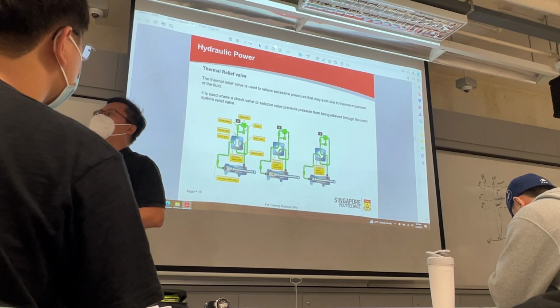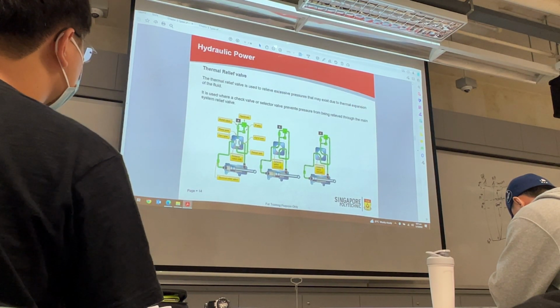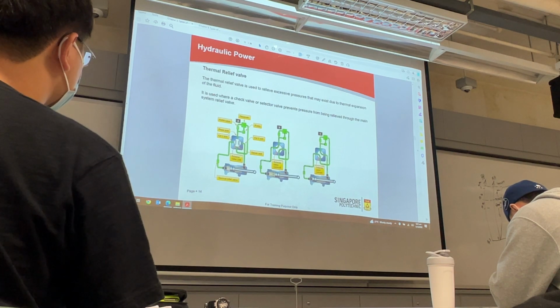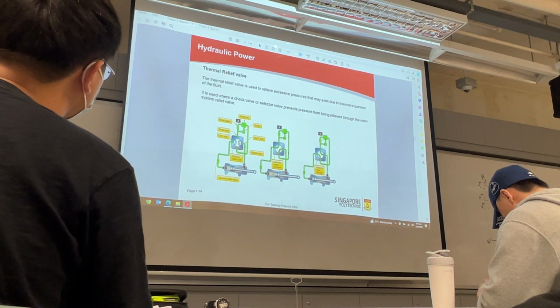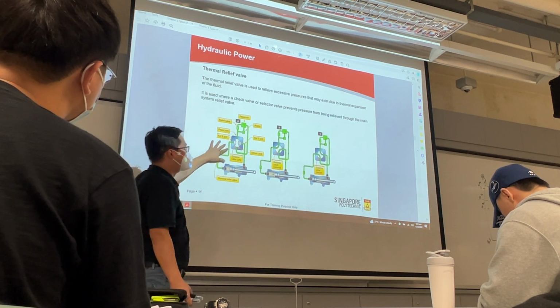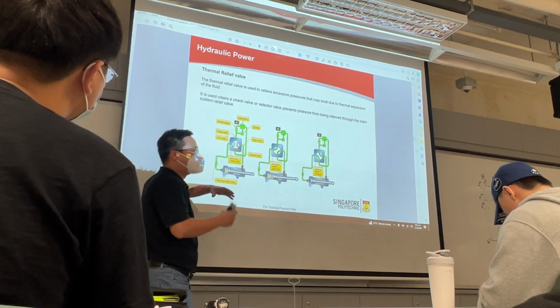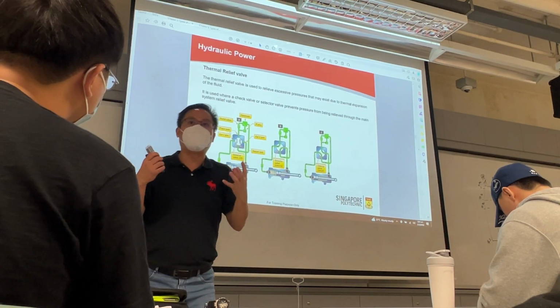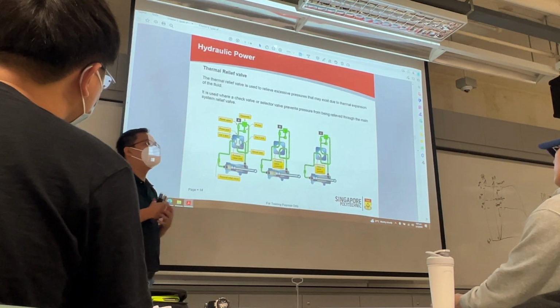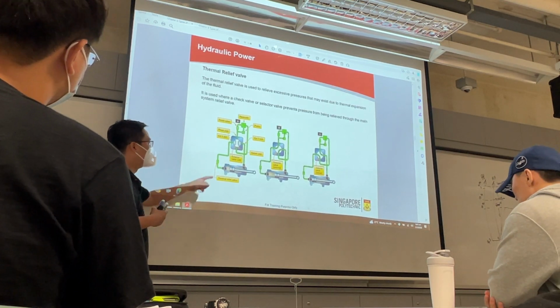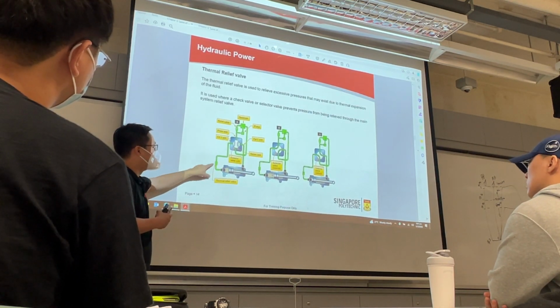When the aircraft starts to land, it will open, and then this piping will be exposed to the environment of the airport. Now, if at higher temperature, the fluid will start to expand. Expand means it has no way out, it may cause the pipe to burst. So one way to resolve this is I will use a thermal relief valve to relieve the fluid over here.